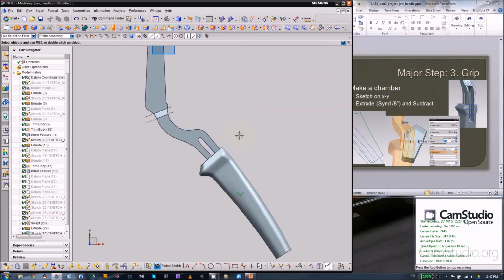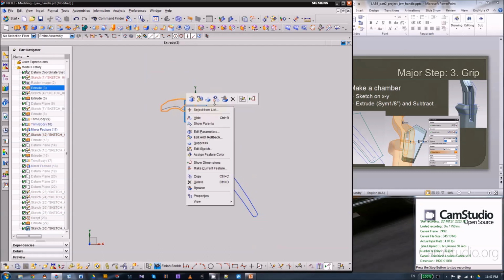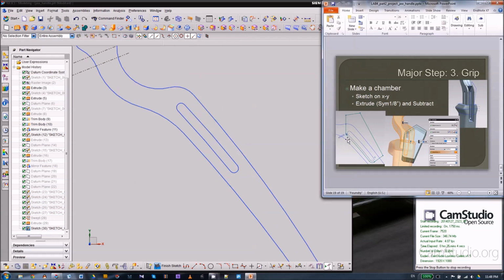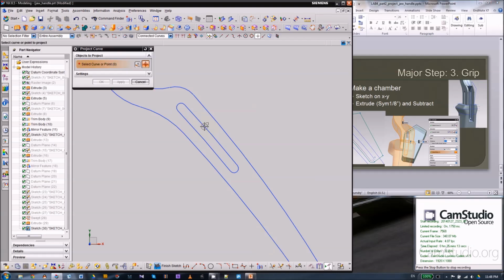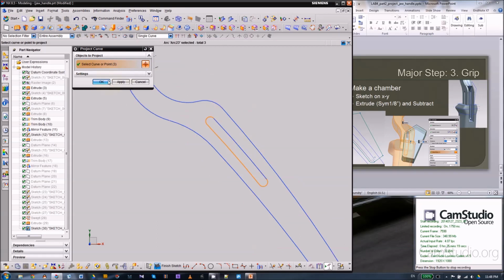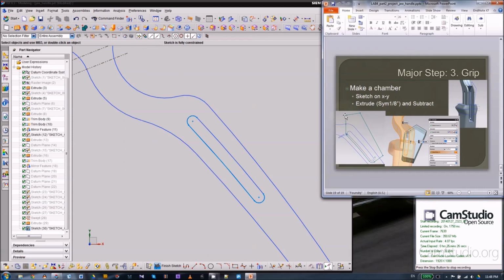Yeah, this is a pretty complicated part, and let's hide everything first. Hide the extrudes first. Okay, so here it's gonna be referring to the slot. So in this sketch we need to project this curve. Project the single curve, this side, and the bottom and top arc. That's all. And as you can see, this line is vertical. That line is not quite, but it looks like it's perpendicular to this arc.